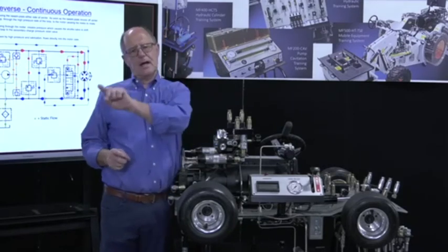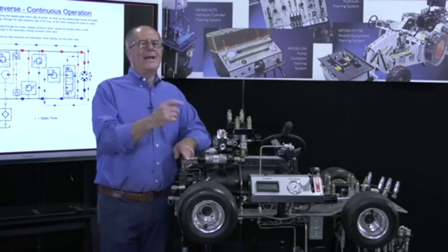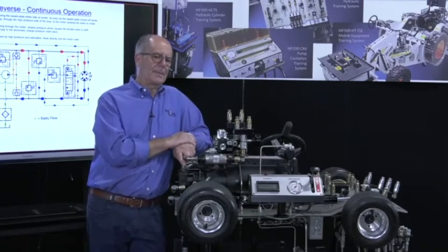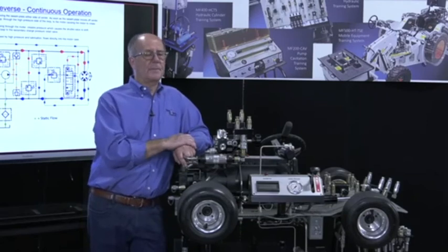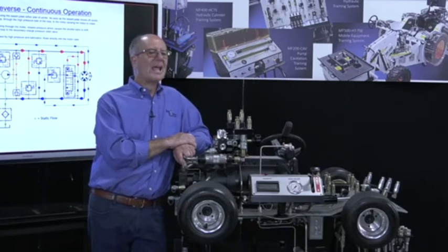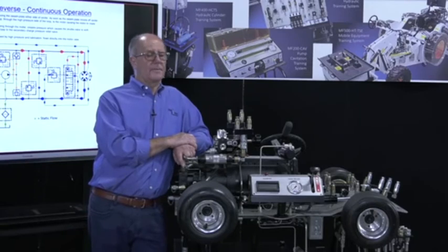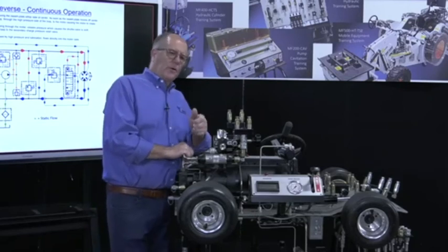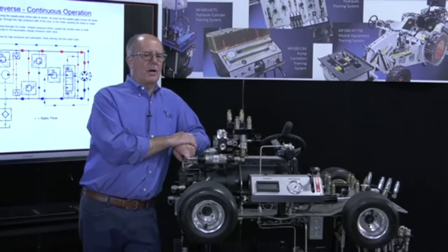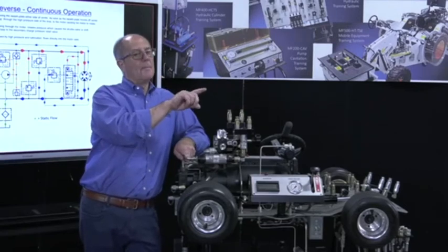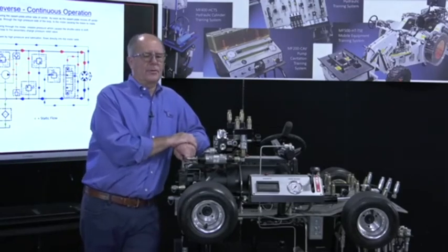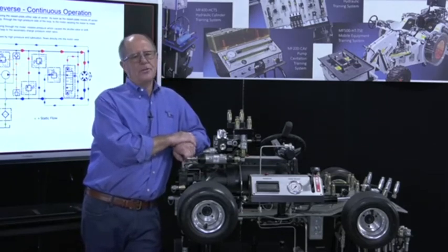In other words, all you have to do is loop a line so that the lines are joined, and then go and put a 0 to 1000 psi filter at the inlet port of the pump. What we call a slave filter for startup. It only needs to be 1000 psi because you're not going to run higher than charge pressure when you start it. What you do then is you start it up, considering now you've got all these steel lines that potentially got contaminants in them, and you go to full throttle, full swash plate angle forward, and you run flow through from the new pump, bypassing your new motor with that line you put in, and then back through the filter, and you do that for about 30 to 45 minutes. And then you do it in reverse.